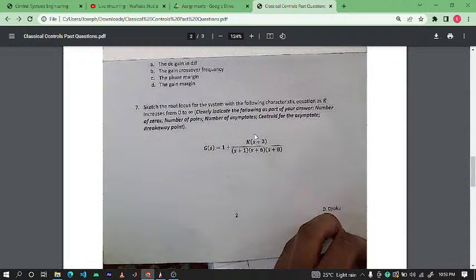There are 3 poles and there's 1 zero, right? They must be equal. So how many zeros will you add to 3? You add 2 zeros, which means that there are 2 zeros at infinity. It makes sense. So it means that here I have 3 finite poles, 1 finite zero, 2 infinite zeros, 0 infinite poles.